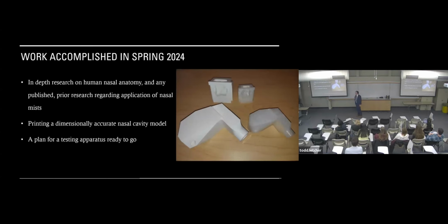As far as what we had accomplished in the spring of 2024, we had developed initial prototype models. As you can see, we then 3D printed them using just Ender 3's FDM technology with simple PLA filament. The one on the left is just white PLA at 100% scale, and the one on the right was a test using transparent PLA filament.